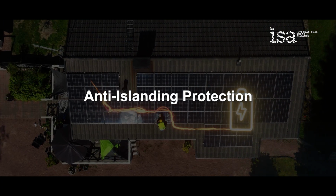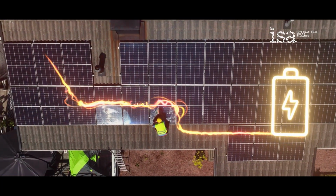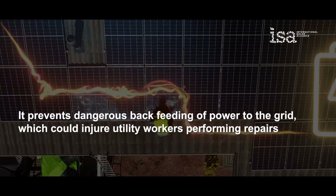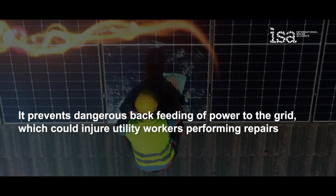Anti-islanding protection. This critical safety feature automatically disconnects the solar system from the grid during a power outage. It prevents dangerous backfeeding of power to the grid, which could injure utility workers performing repairs.